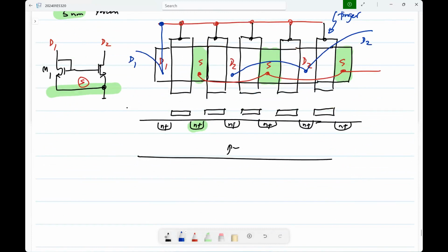So for instance, I can have extra transistors on the side, which are connected to this, but I tie the gate to ground so that they don't carry any current. So you have dummy devices. Basically, the dummy devices should be there to match the physical environment, but they should not electrically affect your circuit. That's the idea. And you can have any number of these.